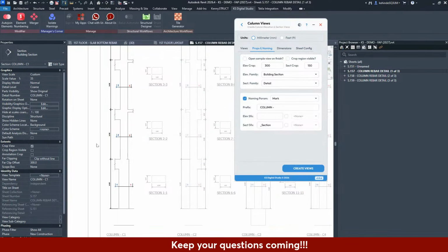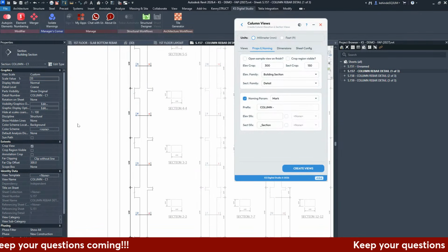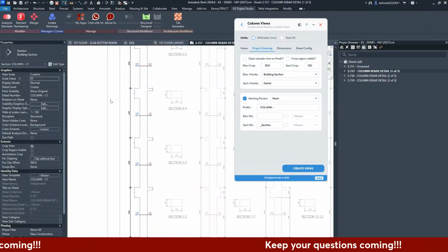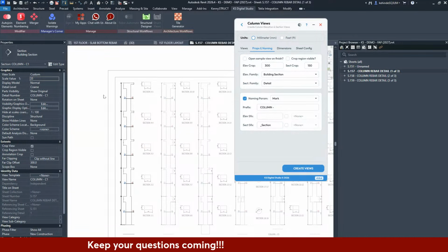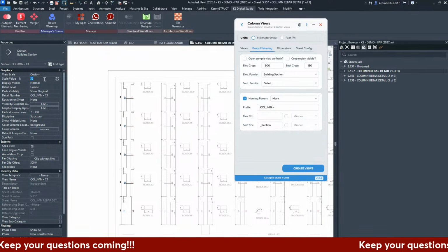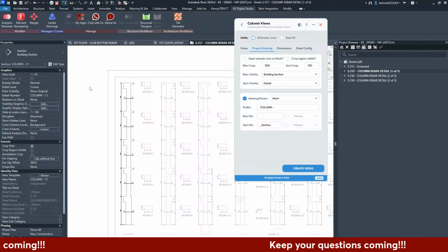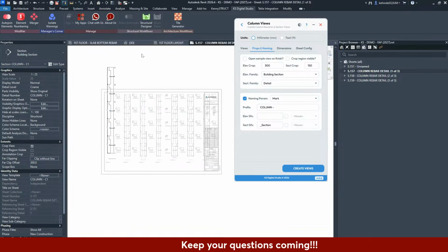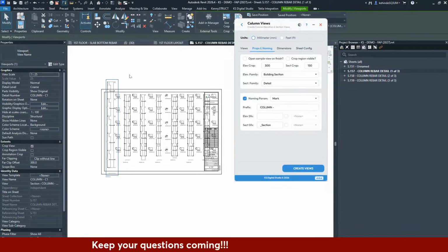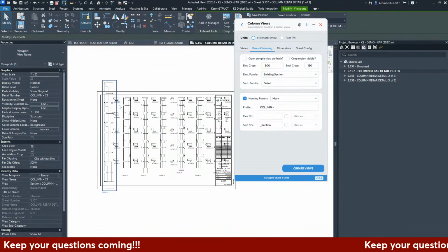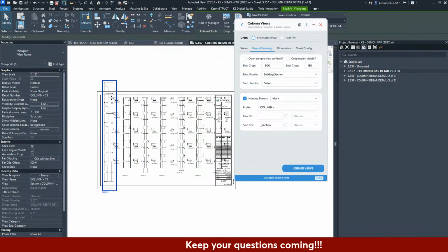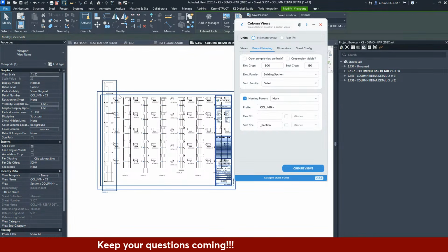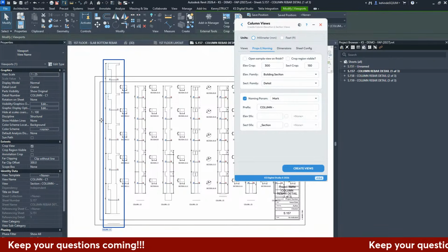Very thin. And I use this scale. Depending on the size of your project, use the scale that works for you. I use scale 35, which keeps it well inside of the sheet. If I use something like scale 30 or 25, it goes beyond the sheets, and in this case, the plugin is going to create 1 column per sheet, which is not really what you want, right? So make sure that you do that one column, then create it as a template. So I will undo now.